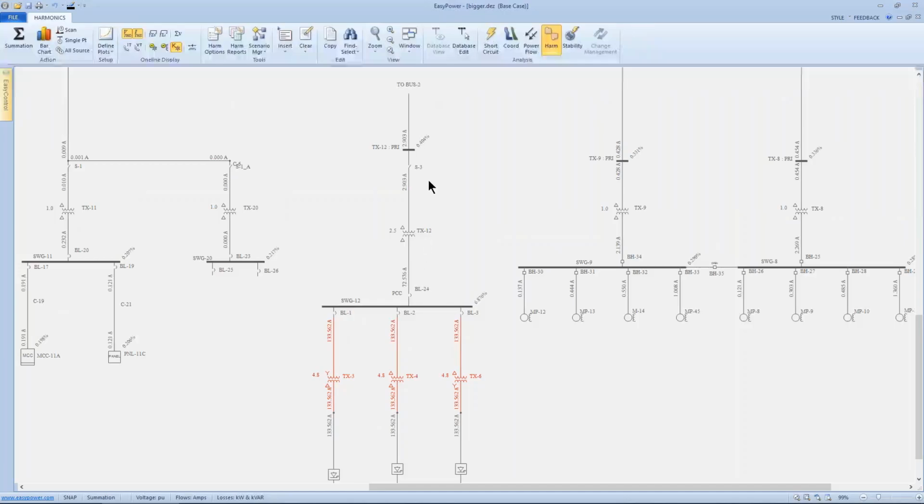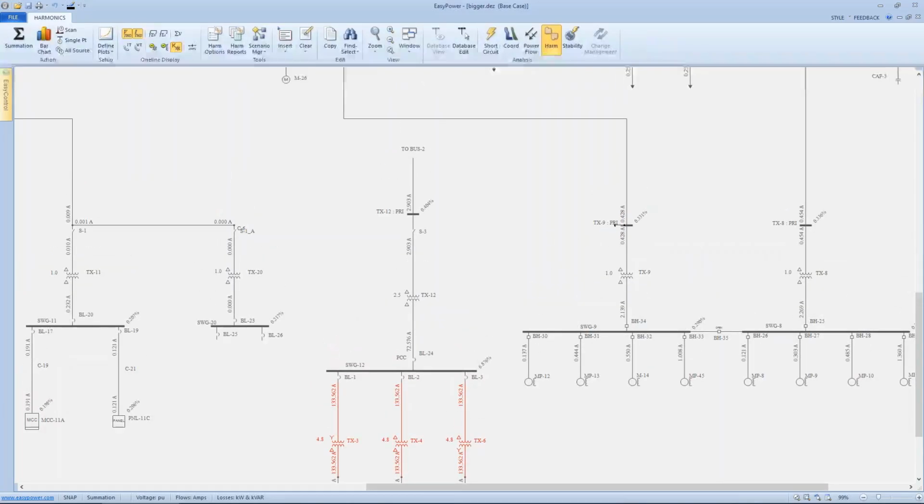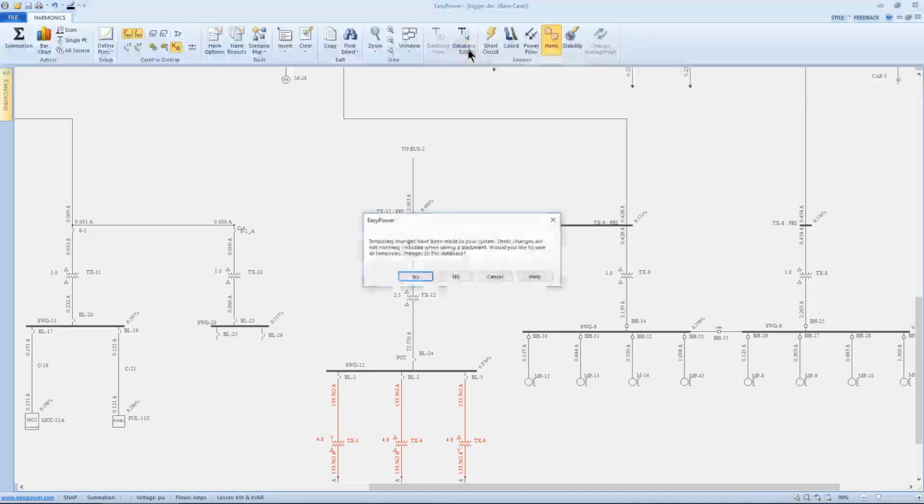Another option would be to filter the frequencies if we don't have that large of a load or that concentrated of a load. We might apply frequency filtering on certain buses. The tool allows us to put that in and simulate different values of the filter.